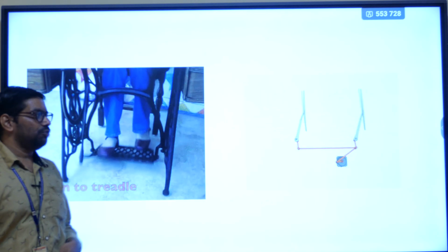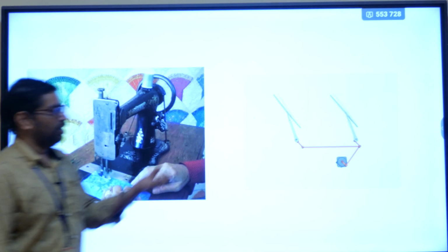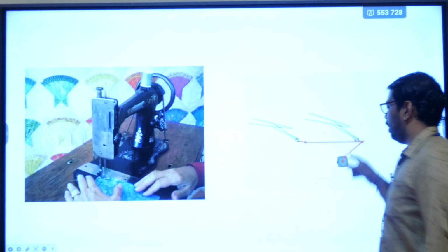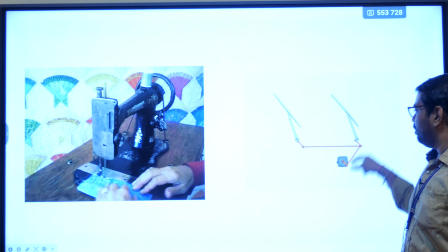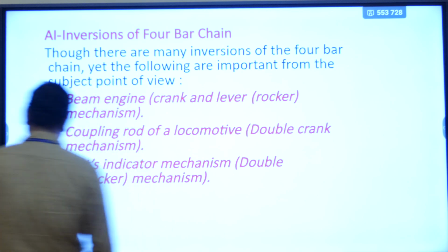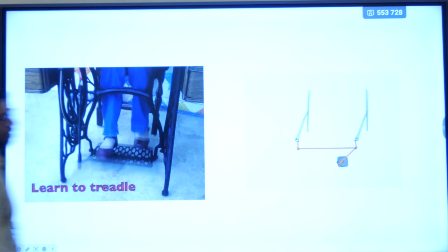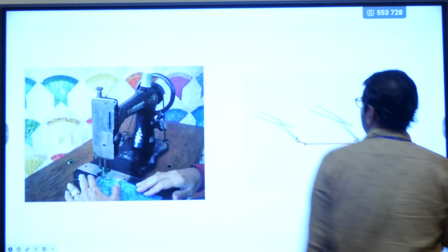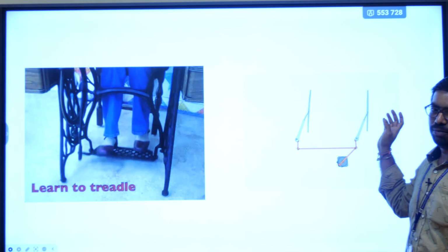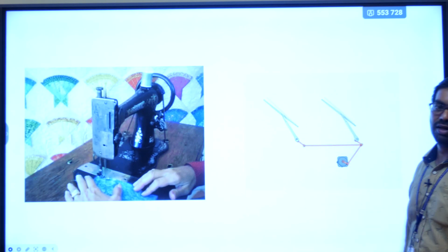So the applications of these particular mechanisms: one is the wiper for automobiles, where we can consider the crank and rocker mechanism. Here the motor rotates and makes the crank rotate, and based on the connections of the other links, the motion will be an oscillating motion, which represents the wiper motion, so that when the rain falls, it automatically wipes the raindrops.